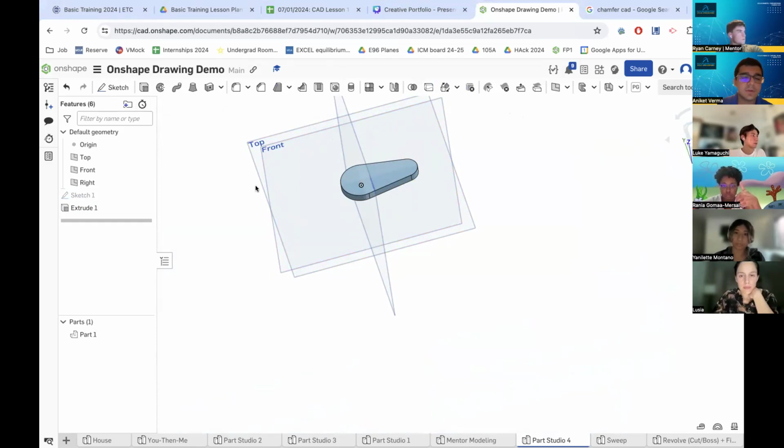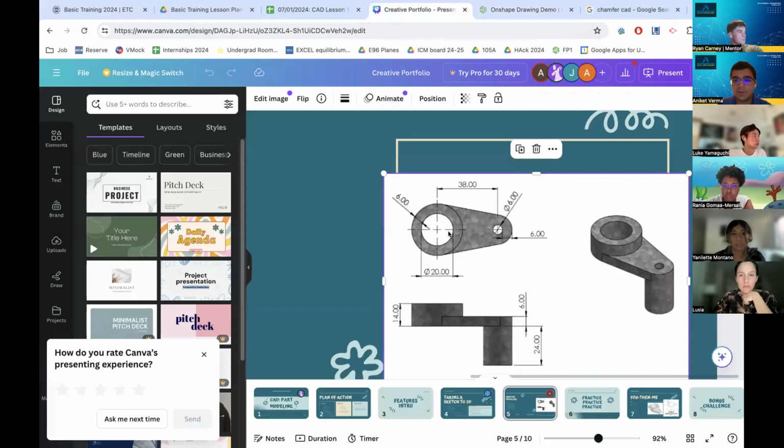Cool. Awesome. The next part of this sketch that I want to complete is this. Let's work on this circular thing right here, the bigger circle on top. So we know that this platform is already 6 millimeters, so whatever additional extrusion we make excludes that 6 millimeters. In this case, we have a 14 millimeter extrusion from the base up here, and then a 6 millimeter extrusion from the base up to here. So whatever extra we need to do has to be 8 millimeters.